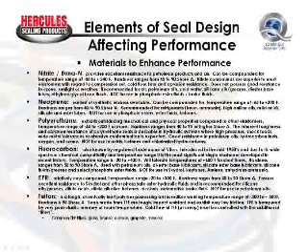Fluorocarbon is another term for Viton. Viton is a trade name of DuPont. Fluorocarbon is a more generic name. It was introduced in the 50s. Temperature range from minus 20 to 400 degrees. One of the primary reasons that you use it is for higher temperature elevations. Also, it is compatible with selected phosphate ester fluids. It cannot be used with Skydrol and some other types of fluids, but it would be used primarily for higher temperatures in petroleum-based fluids and also for some phosphate esters.